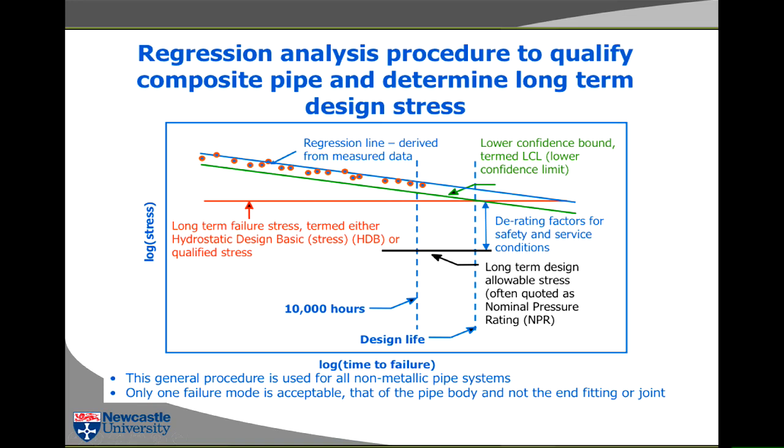And you do that for several different pressures, so you get many different times to failure. It's very difficult to get these long time points, because it's like trying to hit something with a gun when it's far away. It's trying to hit a far away target. You don't know what it's going to be when you're doing the original testing.